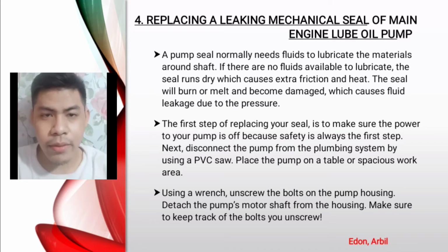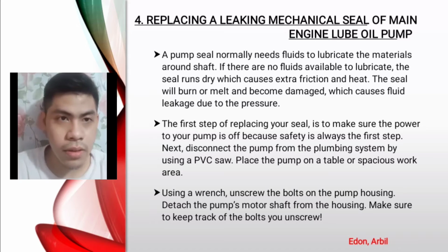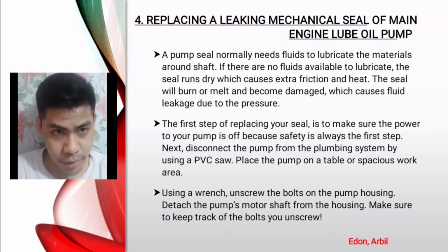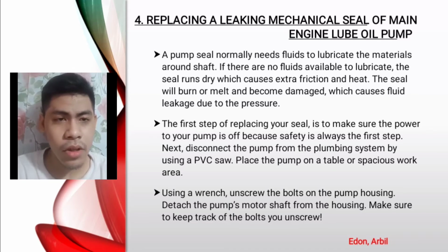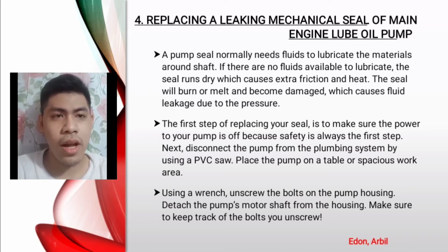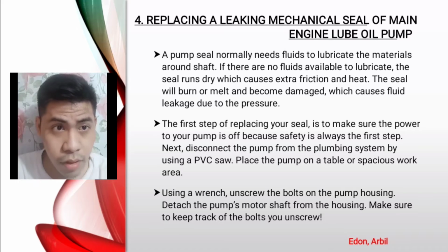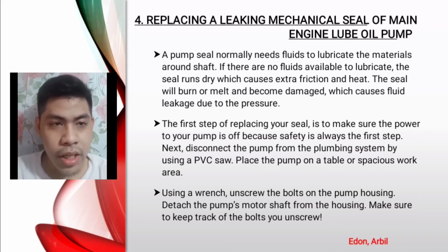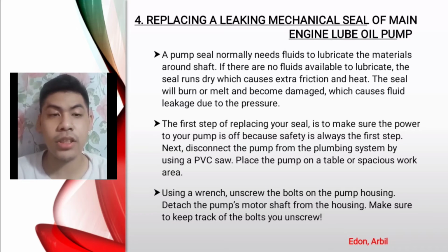I am Engine Cadet Idon, and this is about replacing a leaking mechanical seal of main engine lube oil pump. First, a pump seal normally needs fluid to lubricate the materials around the shaft, and if there is no fluid available to lubricate, the seal runs dry, which causes extra friction and heat. The seal will burn or melt and become damaged, which causes fluid leakage due to the pressure.